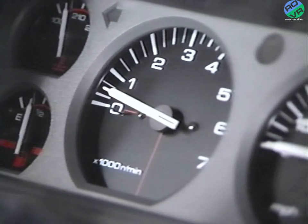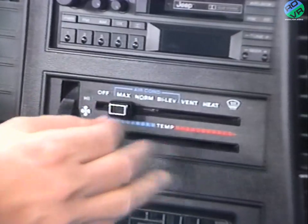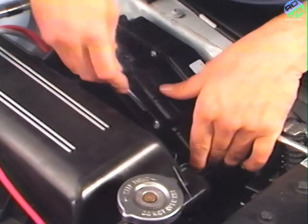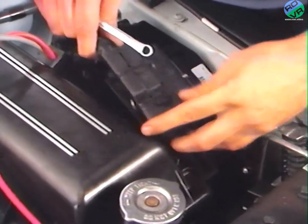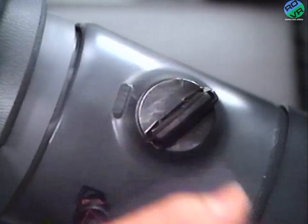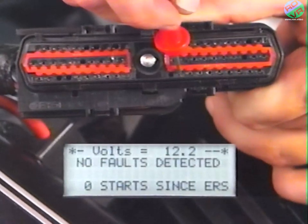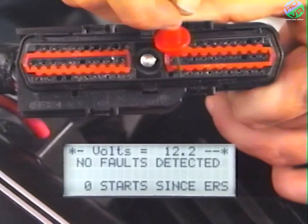If the vehicle is equipped with air conditioning, put the fan on low speed and turn the air conditioning on. If the vehicle stalls when air conditioning is turned on, you'll need to remove and inspect the engine controller connector with the ignition off. If that checks out good, you'll need to turn the ignition key to the on position and use the DRBII in the voltmeter mode to probe cavity number 9 of the engine controller connector, the battery feed to the engine controller, for a 10-volt signal.